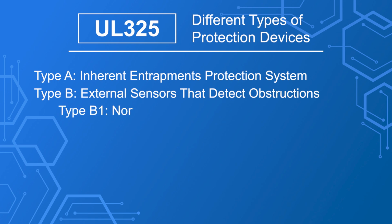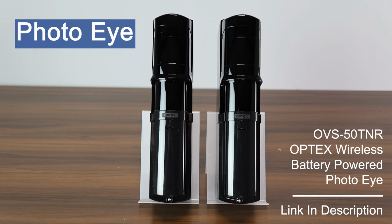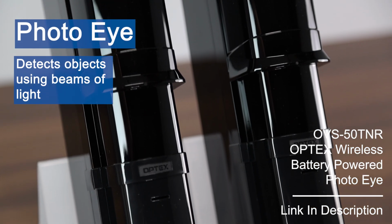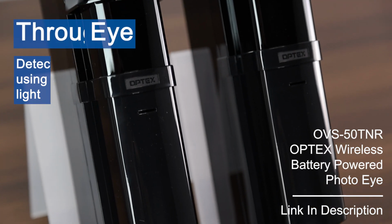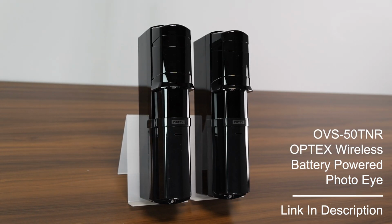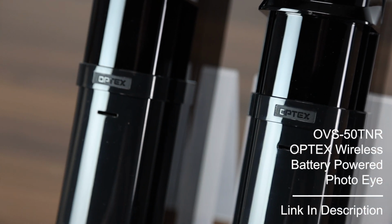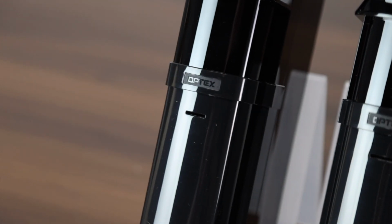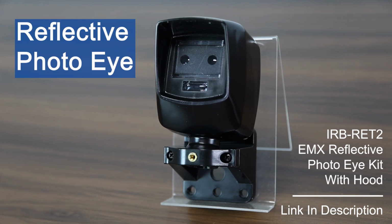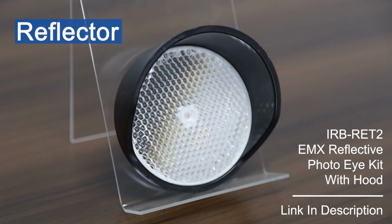Type B1 specifically refers to a non-contact sensor, like a photo eye. A photo eye is a device that can detect the presence of an obstruction using beams of light. This battery-powered photo eye is a through-beam photo eye, which means it utilizes two units, a transmitter and a receiver, that sit across from one another, connecting the infrared light beam from one device to another. Another type of photo eye is a reflective photo eye, which instead has the transmitter and the receiver in the same unit. The light beam is then reflected to the receiver by a reflector.